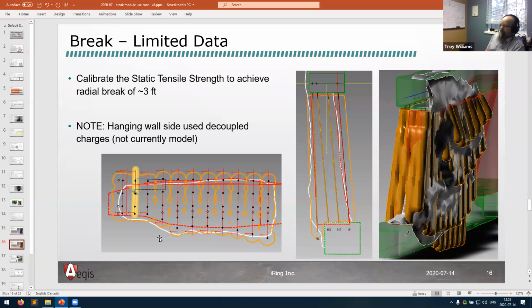And it turns out that they would be able to switch from the packaged product to the bulk emulsion, thereby saving half their explosive costs right there. And in fact, according to our numbers, it looked like the bulk emulsion had a little bit more energy, so they would be able to expand the pattern somewhat, and thereby potentially save drilling costs.